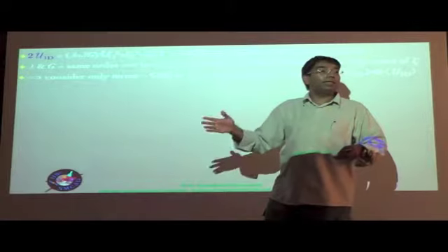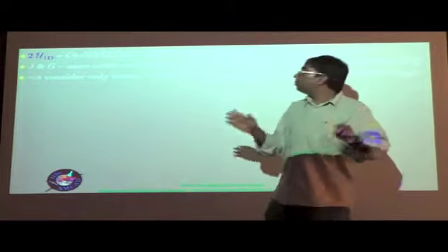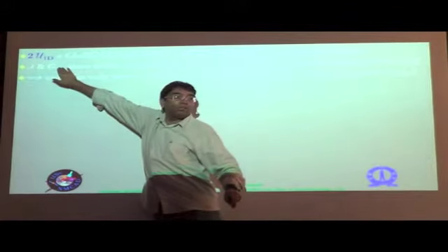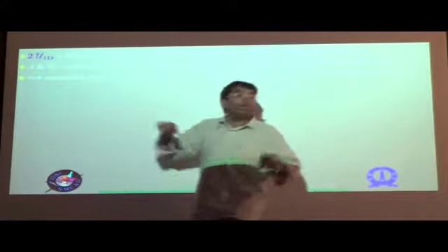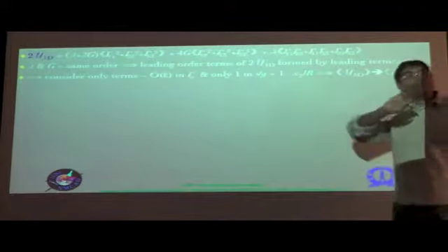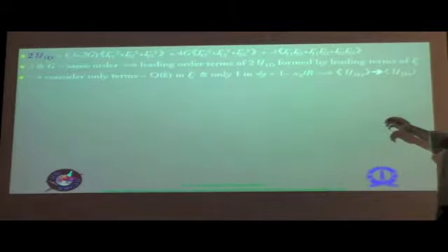In the stricter sense, it has to always be done at the energy level. Because we have a simplified case because of this feature, we are able to do the segregation at the strain level itself, which we already did. That's where we had certain terms not underlined, certain terms underlined, and the so-called HOT or higher order terms, right? So we have already done that.